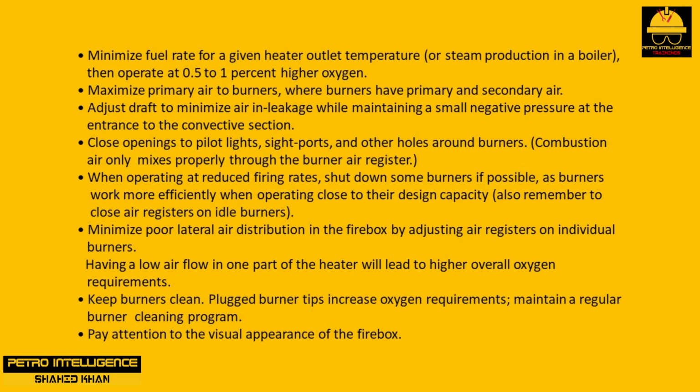Minimize poor lateral air distribution in the firebox by adjusting air registers on individual burners. Having a low airflow in one part of the heater will lead to higher overall oxygen requirements. Keep burners clean. Plugged burner tips increase oxygen requirements. Maintain a regular burner cleaning program. Pay attention to the visual appearance of the firebox.